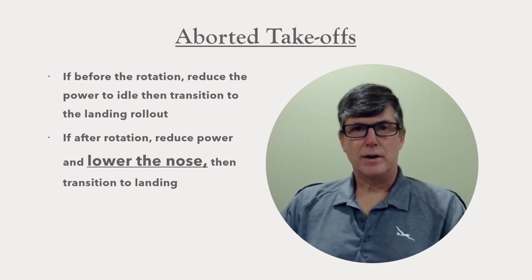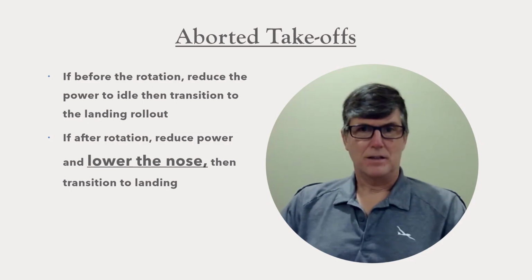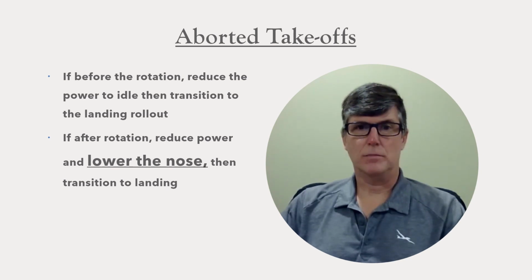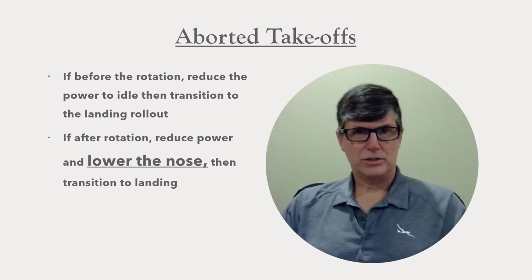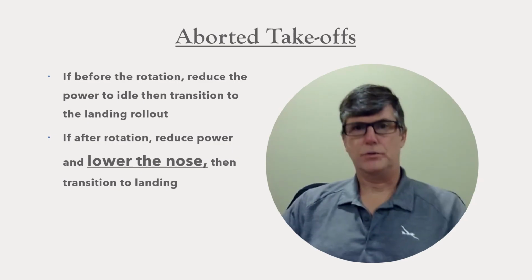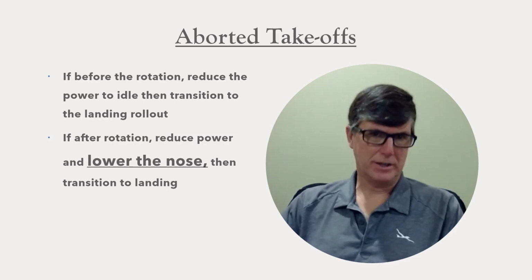Once you're too far along for you to land on the remaining runway, then you shouldn't abort the takeoff unless there's a very serious problem. The correct course of action at that point is very situation dependent. We'll talk more about the different options when we talk about emergency landings later.